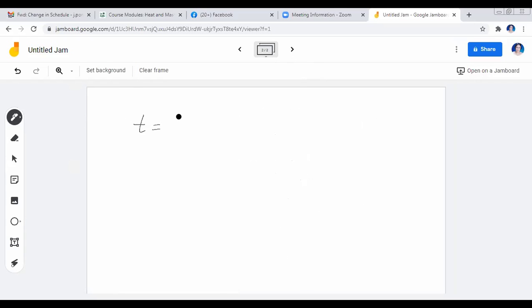So in this case, that would be omega 1 minus omega C over R sub CA. If you notice, this one is for your constant drying rate, or this is for the constant rate drying time. And this one is for the falling rate drying time. So 1 over MA, and this one has the ln of omega C minus omega E over omega minus omega E.